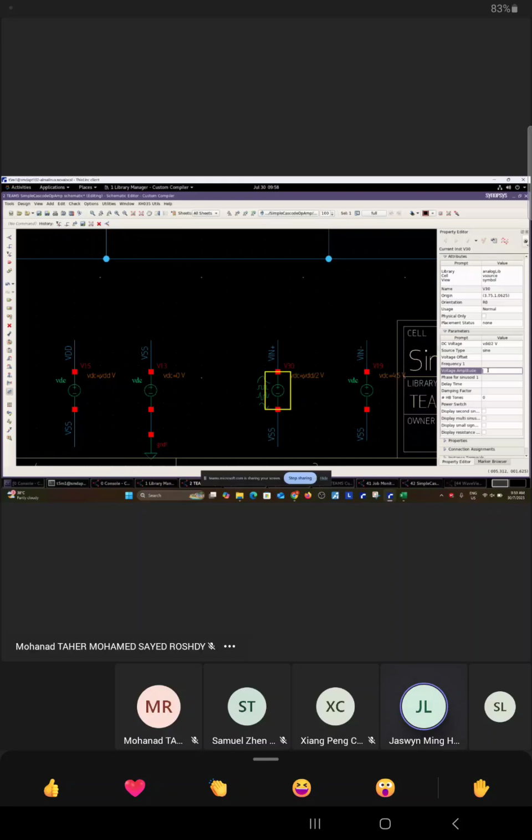Either you set the amplitude to a fixed value, then you see the oscillation of the input waveform, and whether the output waveform is amplified and not changed. If the output is clipped off and becomes a flat line, it means that you have exceeded the voltage swing cap already. So there's one way of doing that, or you can simply plot the peak to peak voltage of the output against the peak to peak of the input voltage.